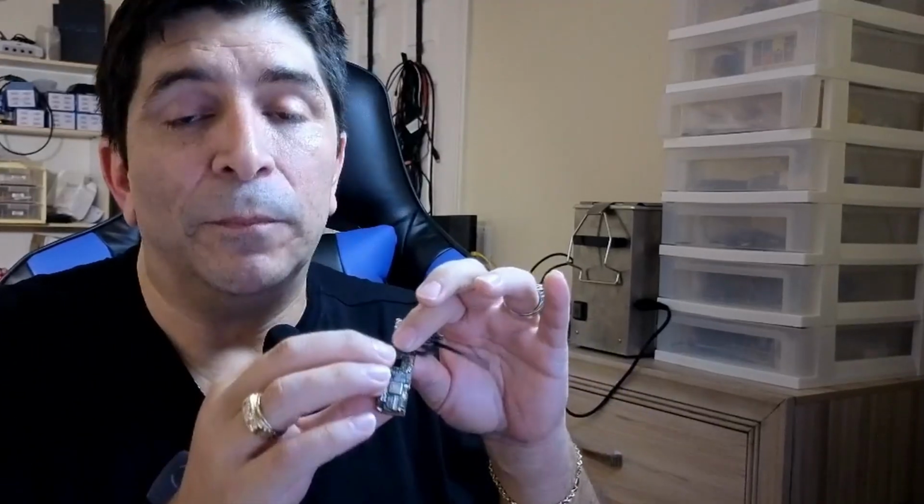So when you get an iPhone motherboard, to get the data out of it, no matter what happens to the motherboard, you have to have three things. You have to have the CPU, the NAND, and the EEPROM all working, and all from the original phone, to be able to get the data out. So if something happened to my EEPROM or my NAND or my CPU, game over. Can't fix it.